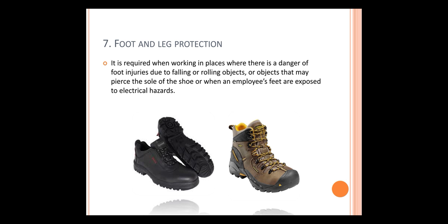This type of shoes must not be used by personnel working near exposed energized electrical circuits. Personnel must avoid wearing 100% silk, wool, or nylon hose or socks with conductive shoes because these materials are static producers. Likewise, foot powders must be avoided because they are insulators and interfere with electrical conductivity.